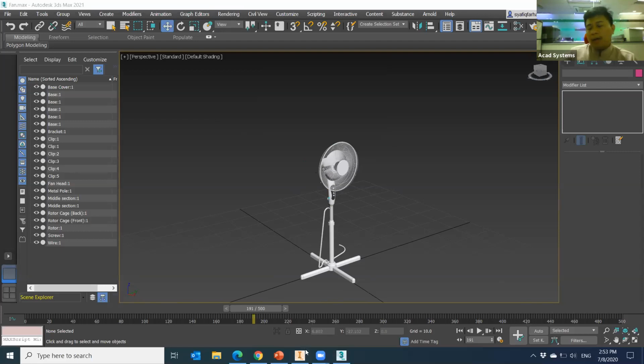You just need to create your assembly using Inventor, and once you're done, you save as IAM and open 3ds Max. Just download your 3ds Max. Make sure your 3ds Max and your Inventor version are the same. For example, if you already purchased the Product Design and Manufacturing Collection, so you already use Inventor 2020, make sure your 3ds Max version is also 2020. Then you just go to file, merge, and import your parts.